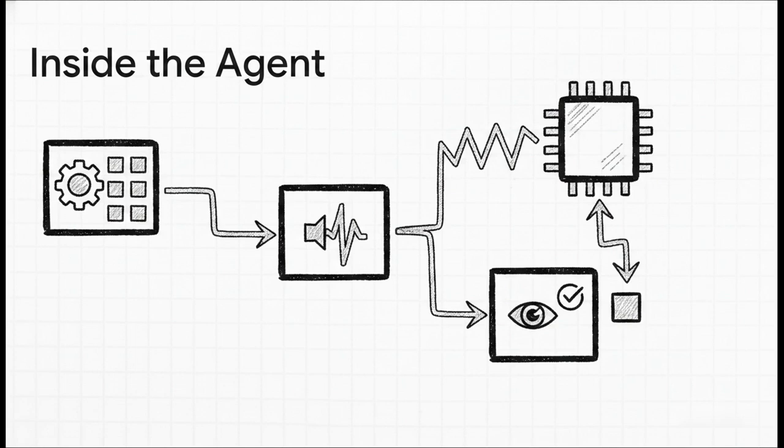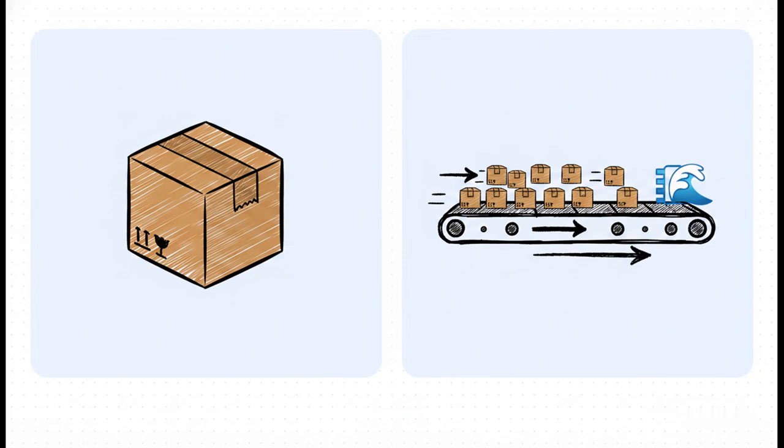And meanwhile, just sitting off to the side is the monitor. It's passively observing the signals coming out of the DUT and translating them back up into high-level transactions so the scoreboard can evaluate them. Real quick terminology check here, because this is pretty crucial to understand.